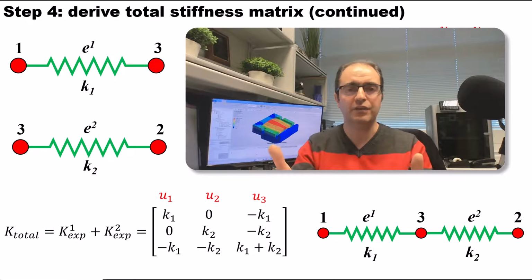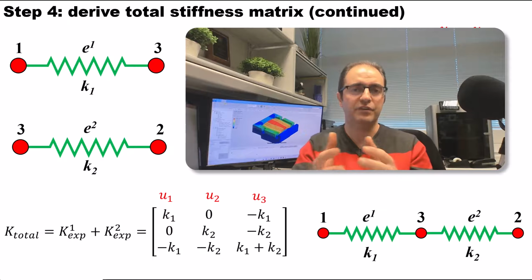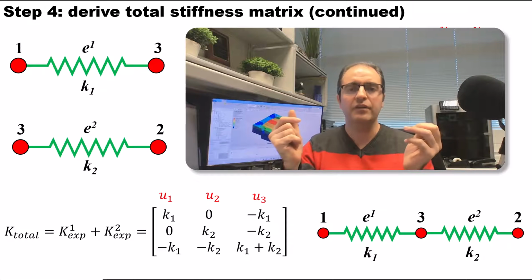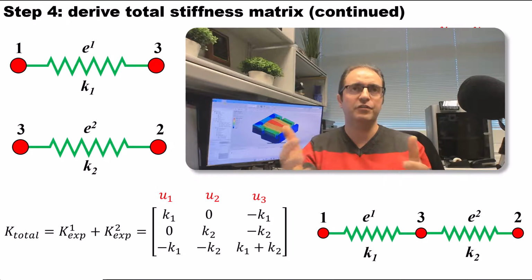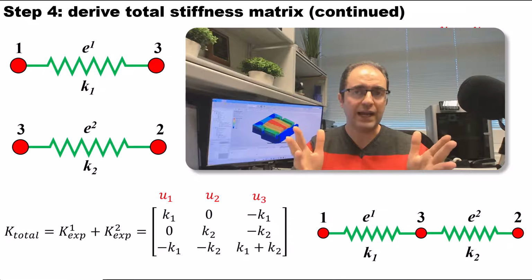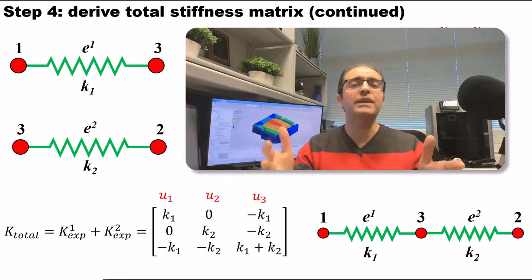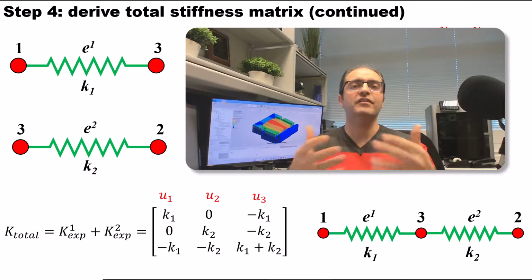That's one of the main characteristics of the stiffness matrices. In many cases in structures, especially in structural mechanics, the stiffness matrices are symmetric. The other fact about a stiffness matrix is that the diagonal terms cannot be negative. Again, physics doesn't allow it.